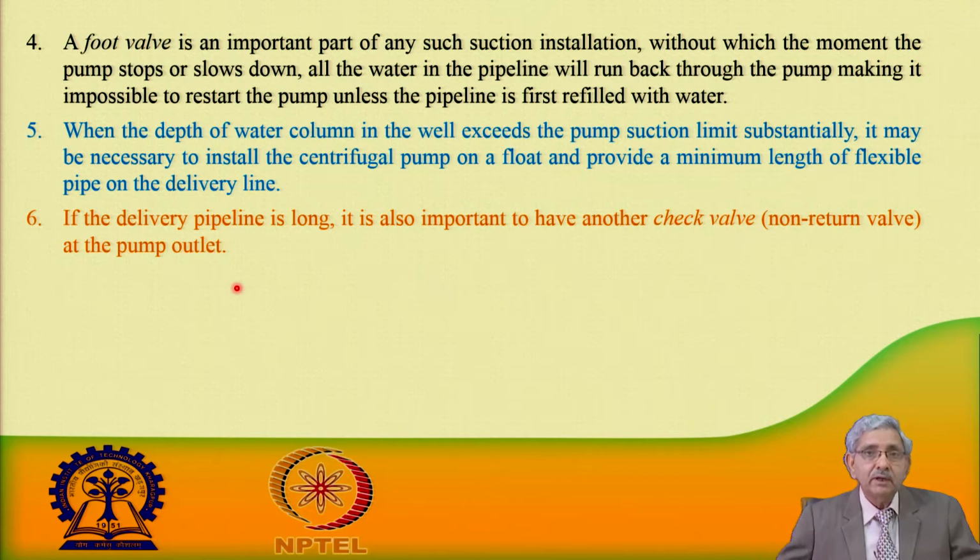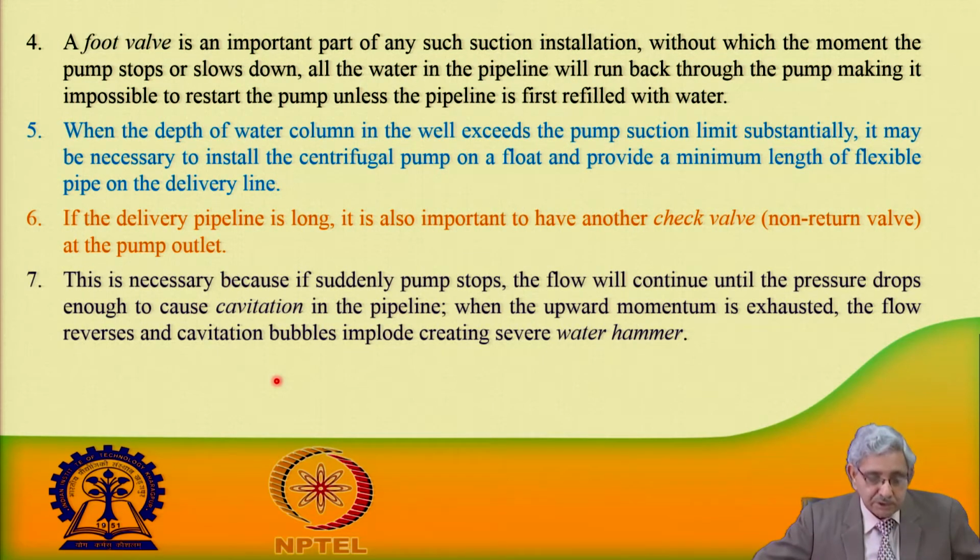So, this will take care that the whole pipeline is filled with water. It is necessary because if the pump suddenly stops, flow will continue until the pressure drops enough to cause cavitation in the pipeline, and when upward movement is exhausted, the flow reverses and cavitation bubbles implode, creating severe water hammer.